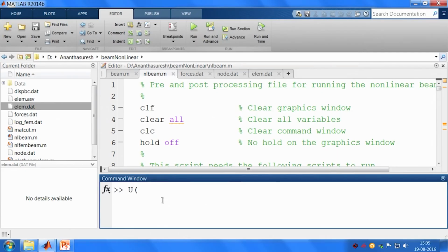So, if I look at U25, that will give me the displacement whatever 9.5313 10 power minus 5, right. If I put this as the first entry 1 entry of the C matrix, I get that, and then I look at the U26, which is the y displacement of node 9, this 5.2712 10 power minus 12, I put that as second one and third one.